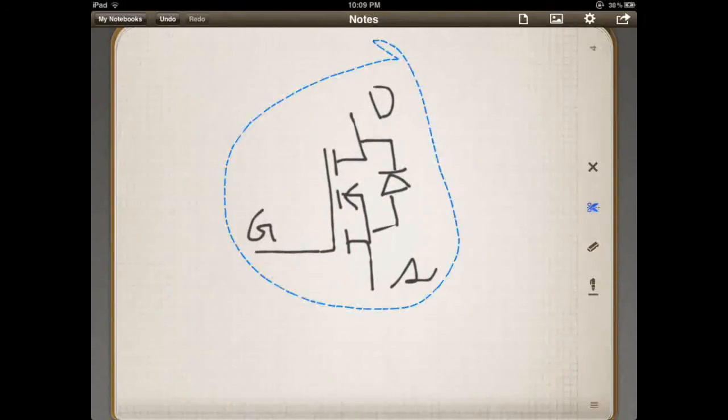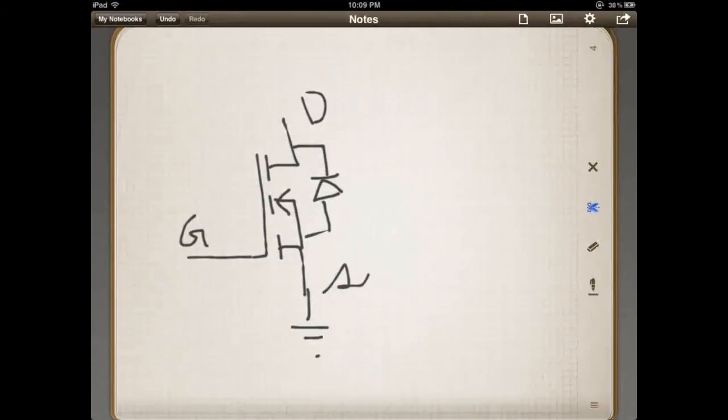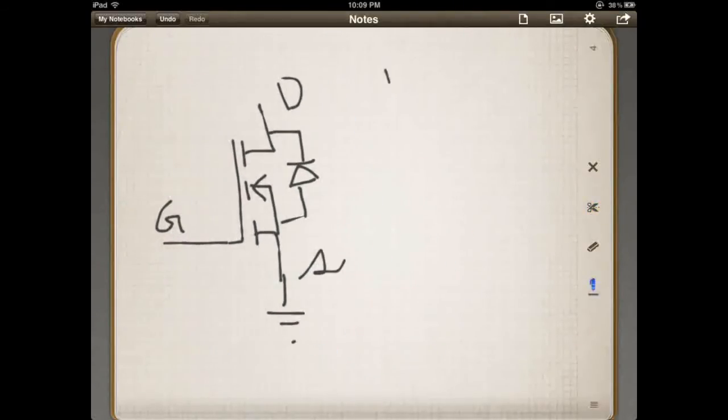And as I said, normally on an N channel device, if we're going to use it as a switch, the source is usually grounded. This provides a 0 because these turn on by a VGS, which is gate to source voltage, which means, let me write this down, I have to take gate minus source, and that will equal our VGS.